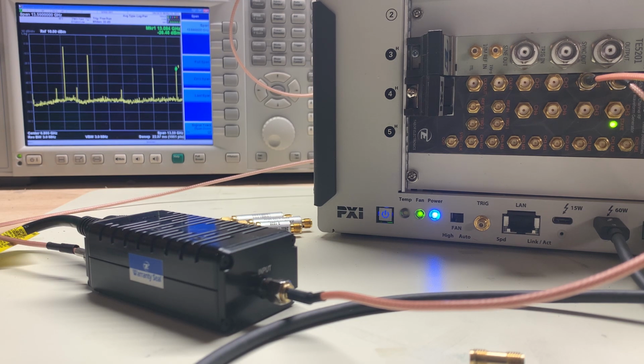I've got the sample clock set to 8 gigs, so we can probably go up to say 3.2 or 3 gigahertz in the first Nyquist zone, and then we would get the equivalent in the higher Nyquist zone that you can see towards the right hand side of the spectrum analyzer screen. And of course we still have the sin x over x roll off.